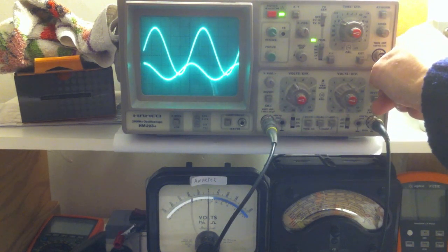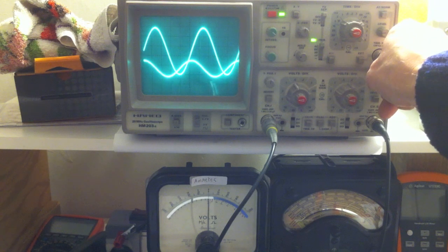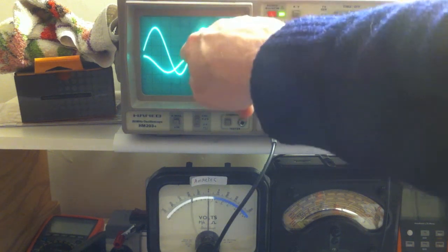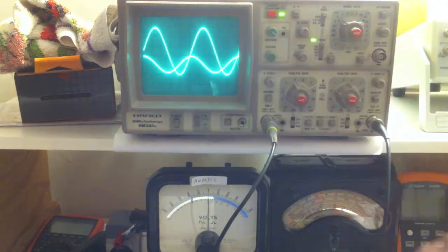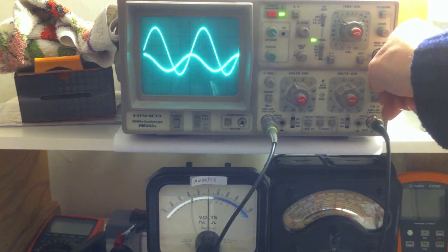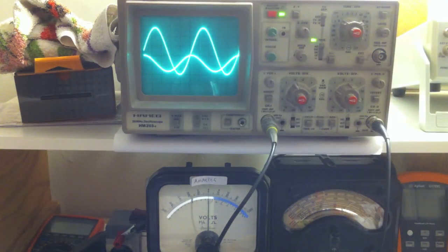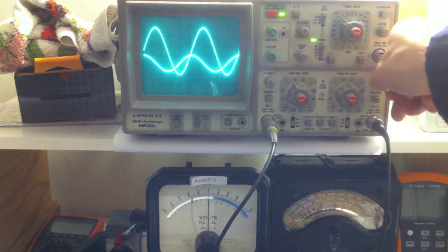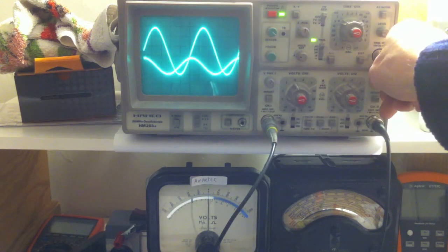Okay, so now you can see if I move this one up, at the fastest rate the voltage is changing, that's when you're going to get, obviously at that point, the capacitor, as it crosses through the center, is completely discharged. So then you're going to get maximum voltage drop across the resistor, and there you go, you can see it, there's the maximum. So I've got the scope fixed up across the resistor on one channel and the scope fixed up on the total V in, which is the voltage across the cap plus the voltage across the resistor, which is this initial curve. And here we can see it.